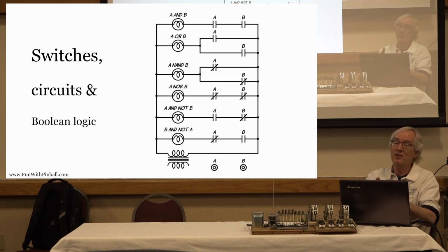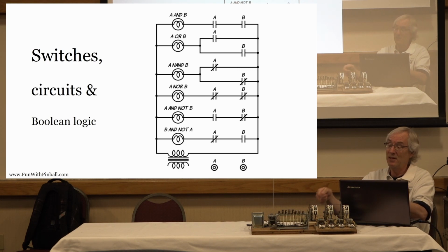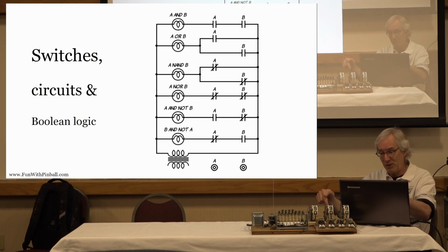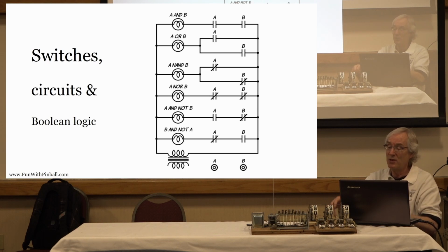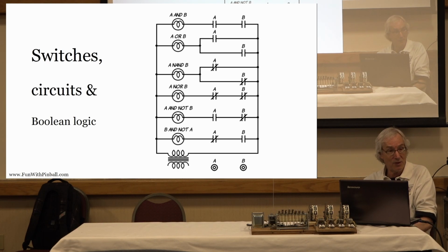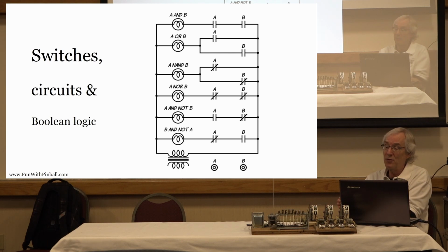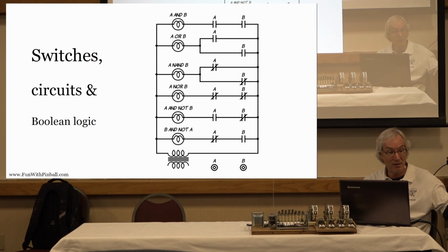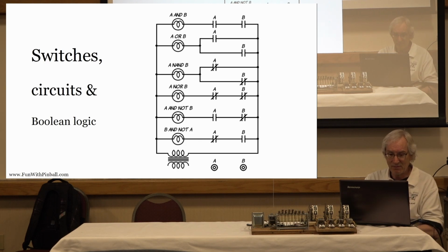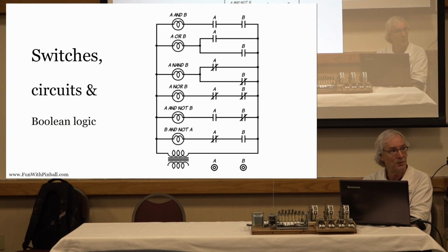Well, if the circuit starts to behave differently when I clip in there, that tells me that my problem is between what I clipped into, right? So if I've bypassed one switch, the problem is likely to be with that switch, because once I remove that switch from the circuit, things start to flow. And that proves to me that all the other switches in the circuit are working, right? So that would be the simplest debugging tool, troubleshooting tool.